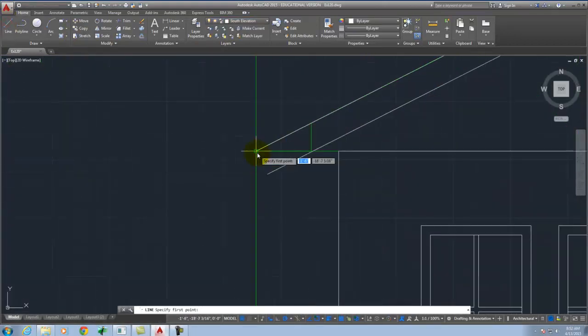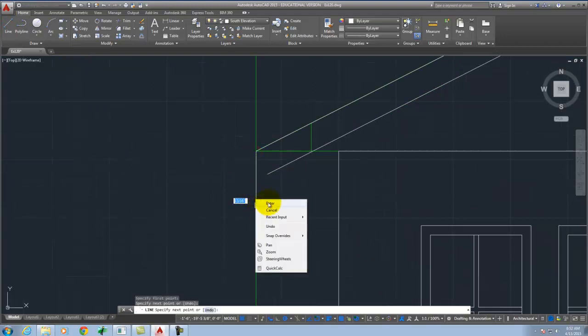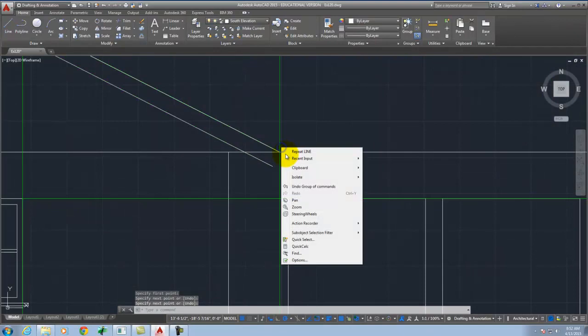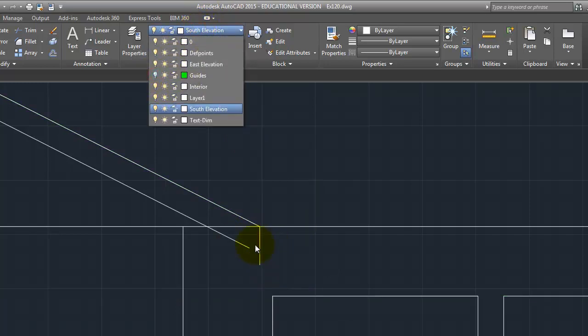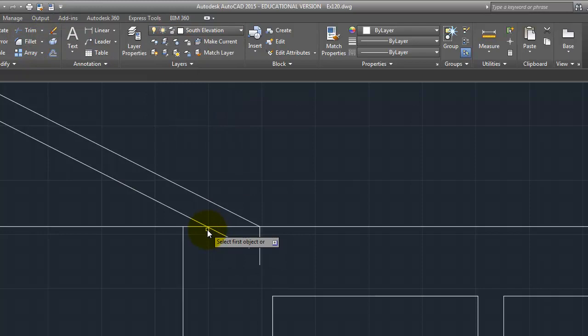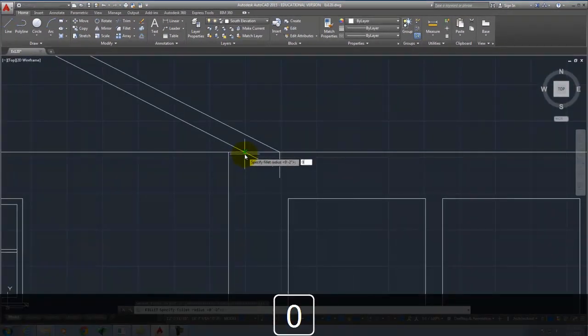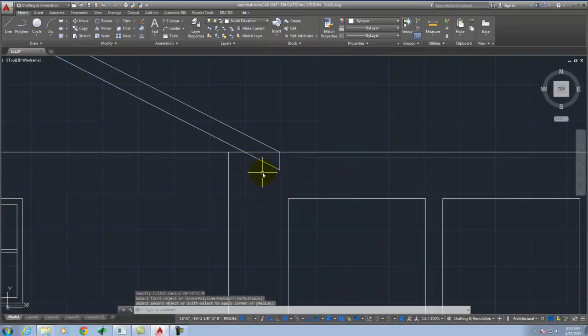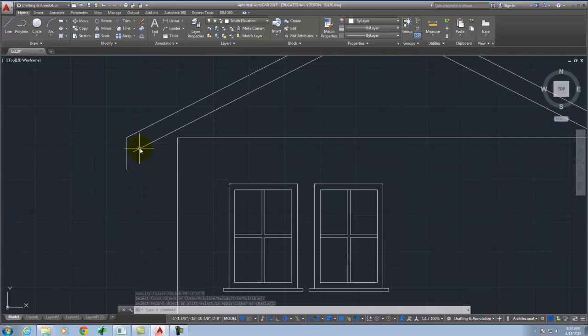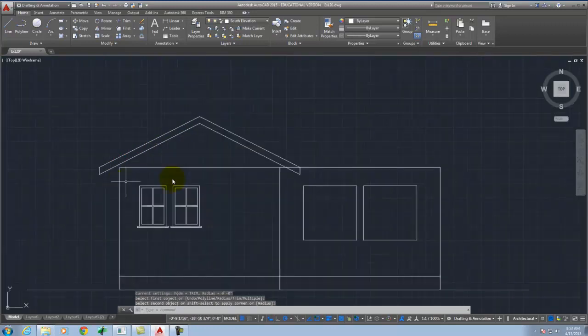When I turn those guides back on, we also know where the end is going to be, so I'll do a line there, and a line there. I don't know exactly where it's going to be, so I leave the line a little bit long, and then I'll turn off the guides again. Remember that trick with the fillet that I did before? I did a fillet, typed R for radius, and specified that it was 0. Then I can click on this line and that line, and it'll come together as a nice little point. It makes life a little bit easier. I could extend the lines instead, but to me the fillet is the fastest way of doing it. So there it is, I have those two pieces.